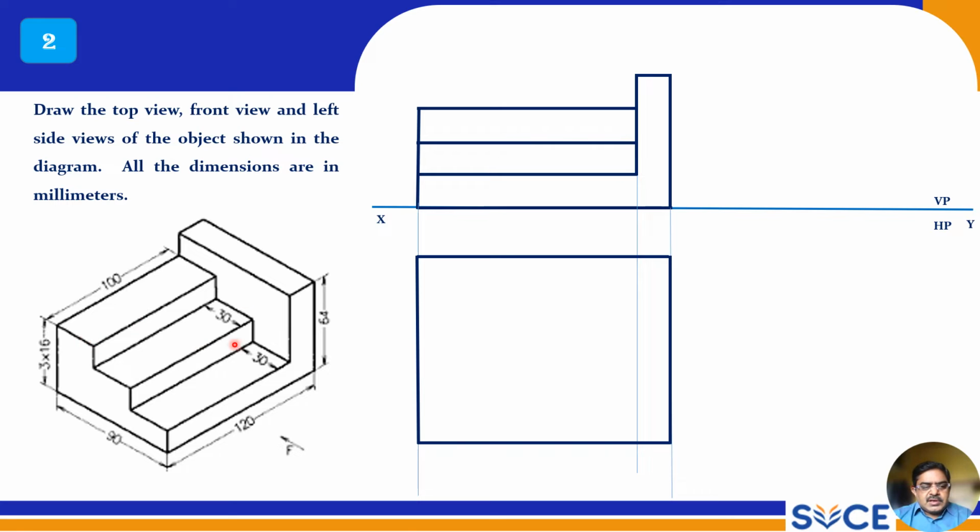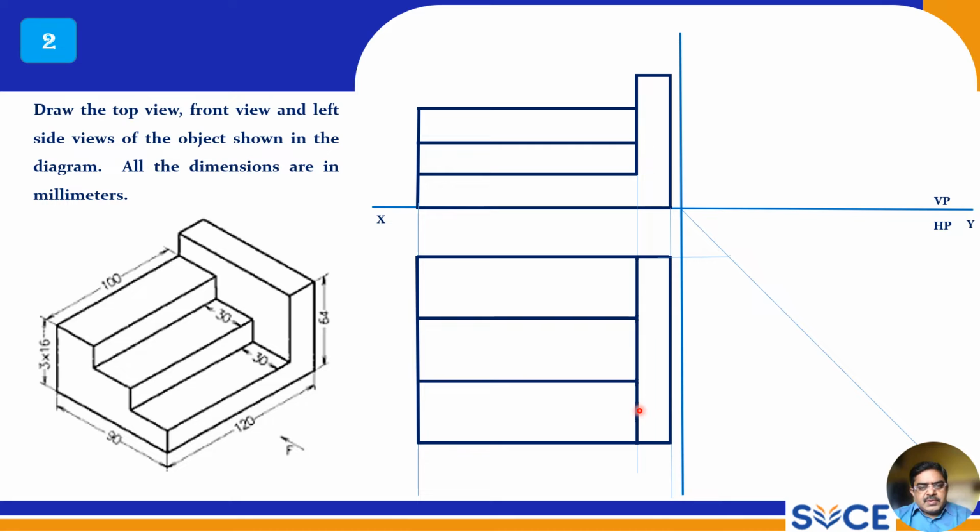Now this is 30 mm, 30, 30, 30. So at 30 mm you can draw three lines, right? So this is visible as a thick edge. At 30 mm you can draw two more lines. So this is your top view. Now draw x1 y1 line, draw the 45 degree line, from all the corners, right? All the points, edges, corners, you draw the projectors. Now project them to the side view. So the left side view is possible.